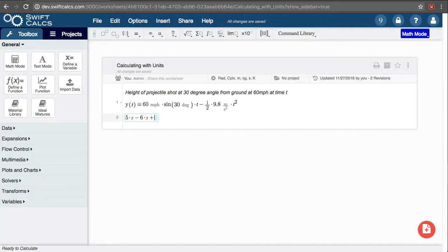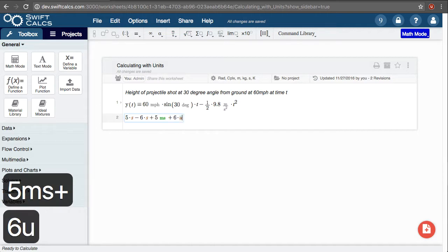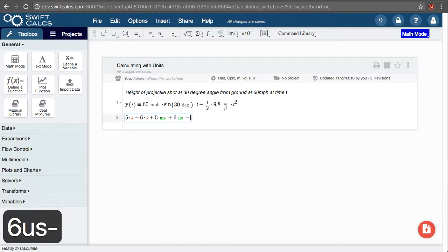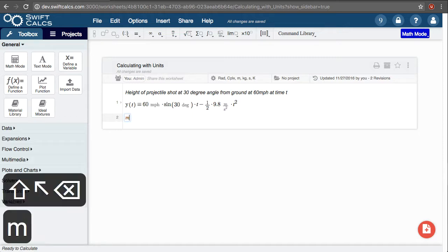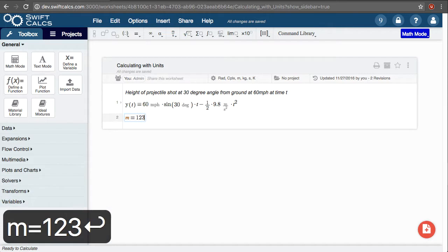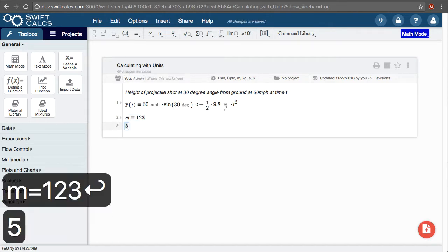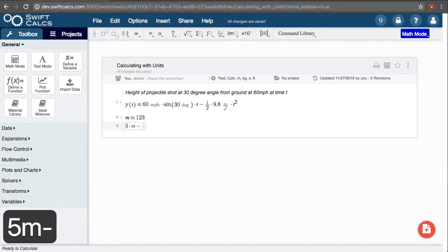The auto-conversion also supports metric prefixes. For example, ms will turn to milliseconds, where a us will turn to microseconds. The u is shorthand for the micro prefix. It's also important to note that auto-conversion will recognize if a variable with the same name as a unit has already been defined. If so, when using that variable name, it will not auto-convert to the associated unit.